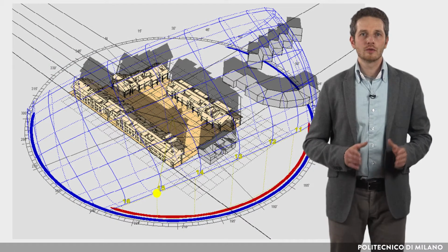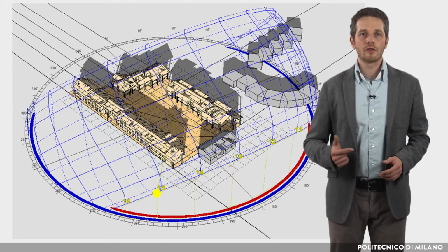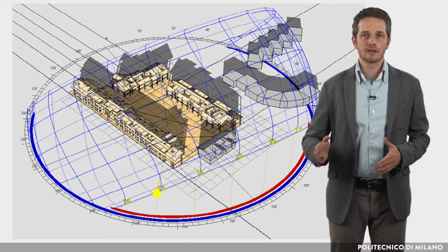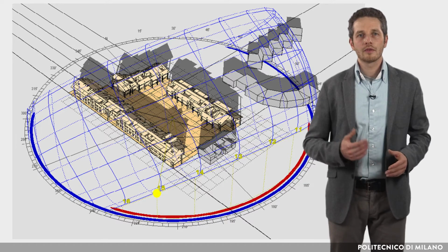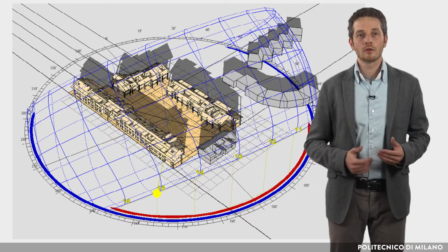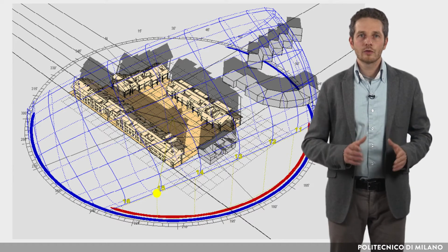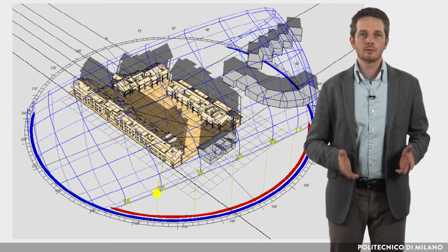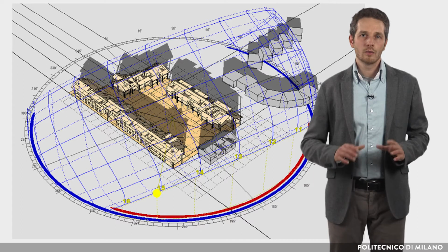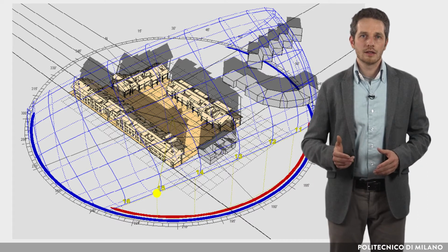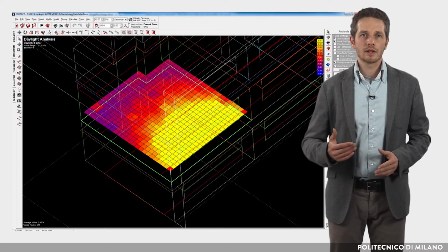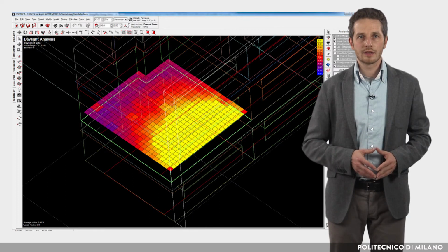Even if it seems to couple an intuitive 3D modeling interface with extensive solar, thermal, lighting, acoustic, and cost analysis functions in a comprehensive and simple way, Ecotect can't provide a reliable numeric simulation of those items. It is very useful for a realistic and expressive shading analysis and for building models to be processed into Energy Plus, with many limitations, Radiance and ASIM, and it can import and show their output in a calculation grid that makes results easy to understand.